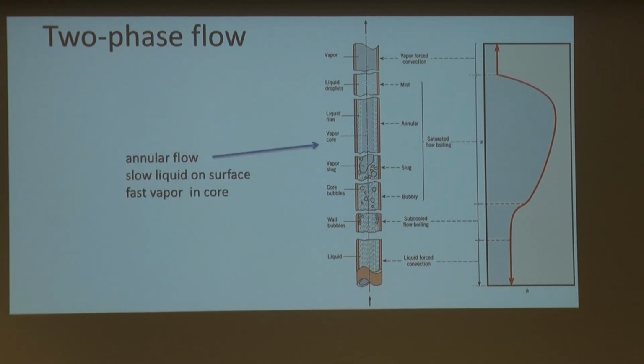Now, at the next stage, it's not a bubble anymore. It's kind of funny how we went from a liquid that had some bubbles to just vapor that is surrounded by liquid. So we essentially have a wet surface on the pipe, but we have vapor going inside.